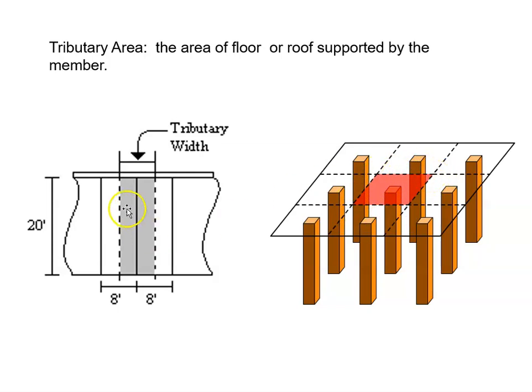Okay. Here we see the solid lines are joists. So I see 1, 2, 3 joists are tied to this wall. These curved lines are just telling us that the drawing is kind of ending. There's another beam supporting them here. So this is a 20-foot joist running from here to here. So it's supported here and it's supported here. 20-foot joist, 20 foot, 20 foot. Now these two joists are 8 feet apart, and these two joists are 8 feet apart.